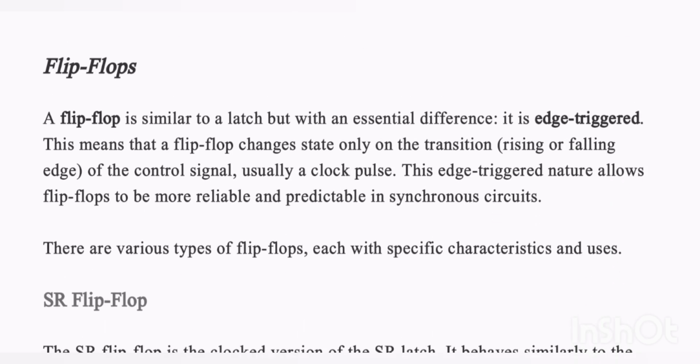Flip-flops. A flip-flop is similar to a latch, but with an essential difference. It is edge-triggered. This means that a flip-flop changes state only on the transition, rising or falling edge, of the control signal, usually a clock pulse. This edge-triggered nature allows flip-flops to be more reliable and predictable in synchronous circuits. There are various types of flip-flops, each with specific characteristics and uses.